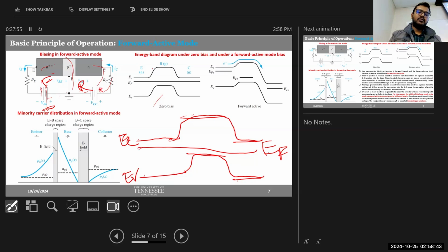And we also know about this barrier, right? This is because of the depletion region here. In PN junction, if you remember, we had the same type of barrier. We call that built-in potential. Do you remember that term? We had that built-in potential, which we had to break to make any current flow, so we had to apply something greater than 0.7 volt. So this barrier is actually this built-in potential. And you also know that when we bias a PN junction in forward bias condition, does this barrier decrease or increase?